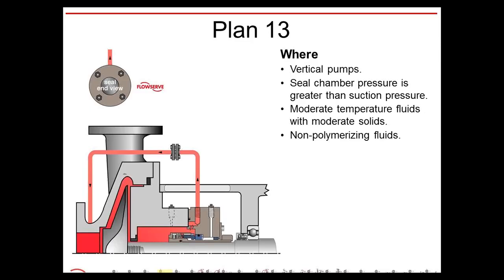This is good to use in moderate temperature fluids with moderate solids. Like I said, if you have solids, and you can't do anything besides a process flush, you want to use the Plan 13. And again, non-polymerizing fluids.